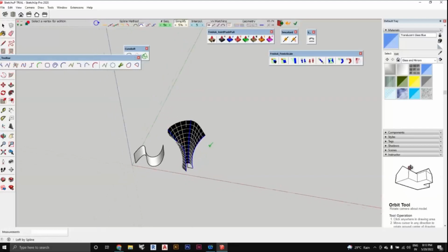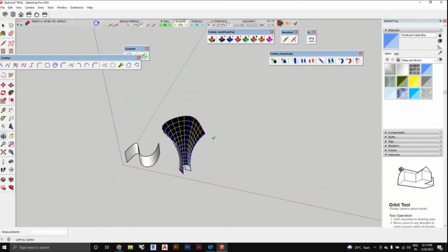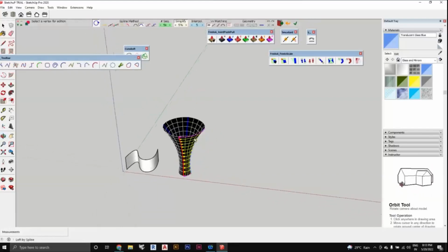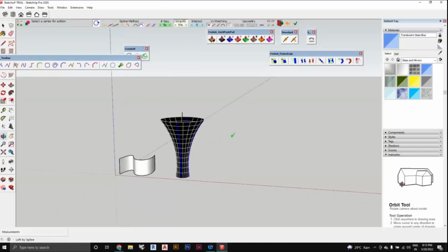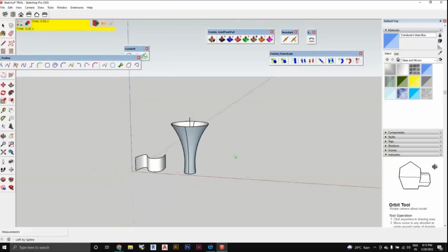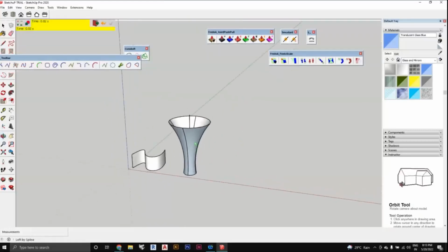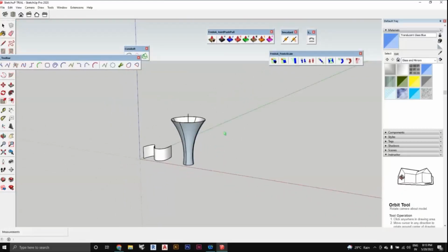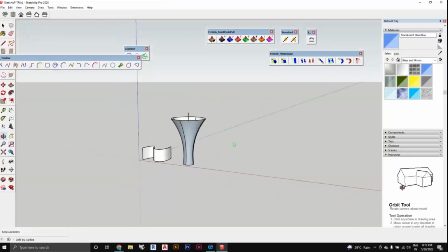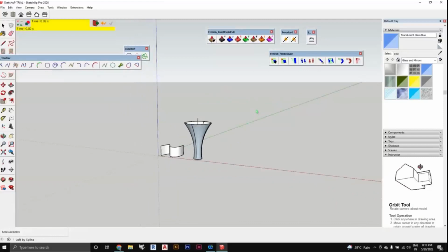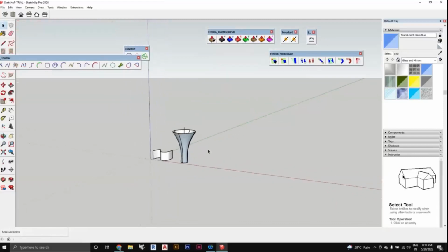What it does is try to create a closed surface. That is the use of this option here. If I press that, you can see that it gets closed. Then if you click outside, you can see that such a mushroom column that I was telling you about gets formed. And again, if you click out, you will escape from it.